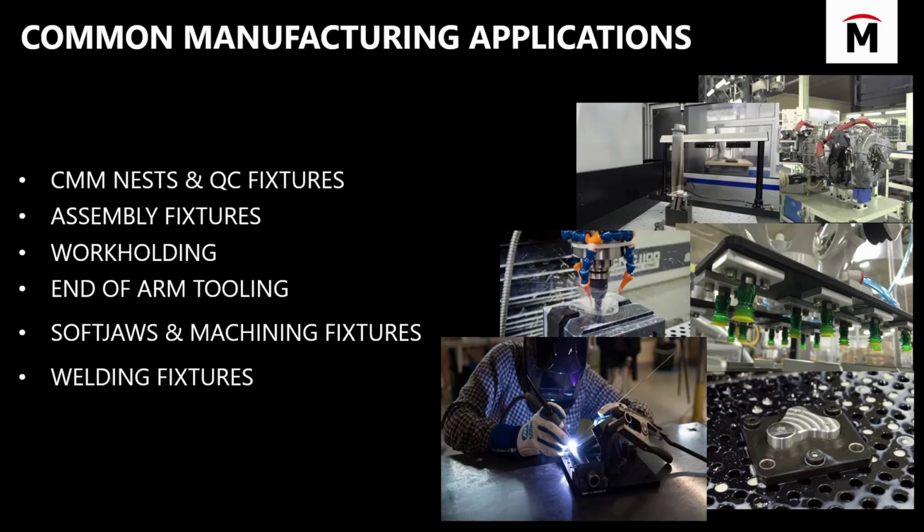Assembly fixtures are typically in low quantity and often very expensive because of the low quantity. And so that makes that a great application. Next is end-of-arm tooling. This just cries out for 3D printing. It enables you to integrate things like internal vacuum channels, air cooling, or non-traditional shapes with extraordinary strength, so you can pick up those crazy little parts or move them with that robot.